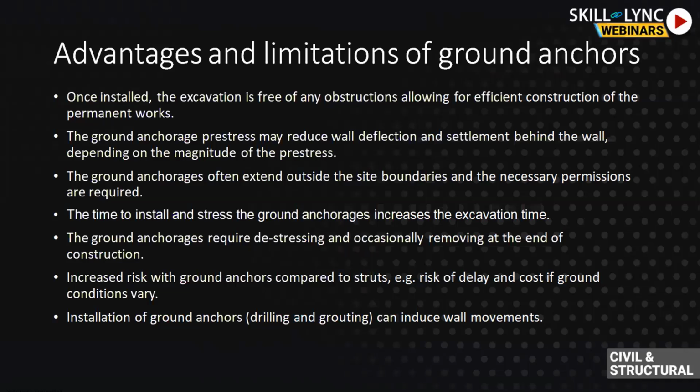Suppose our construction is limited and we don't have right of way. When we go for deeper excavation, the anchor length will increase for the fixed length and free length. To reach that fixed length, you have to go beyond the excavation area. So we should understand that nearby there shouldn't be any pipe, foundation or other construction activities that can be affected. The installation of these ground anchorages also increases the time compared to struts.